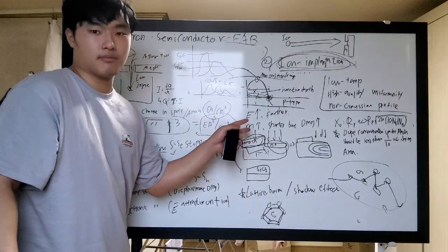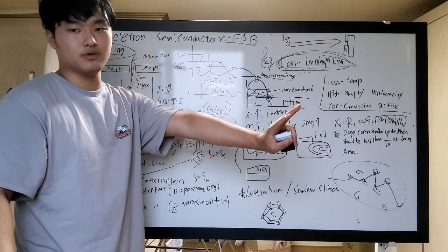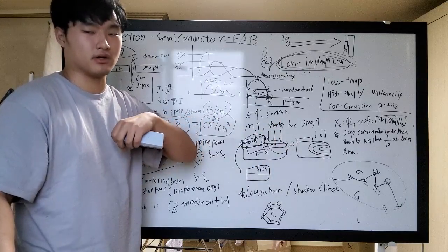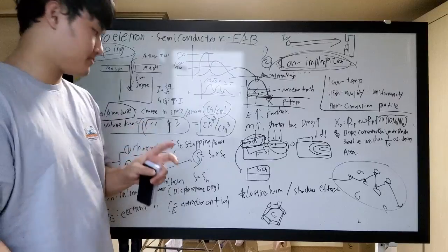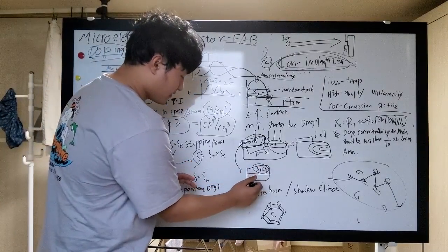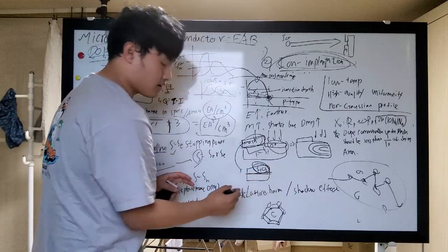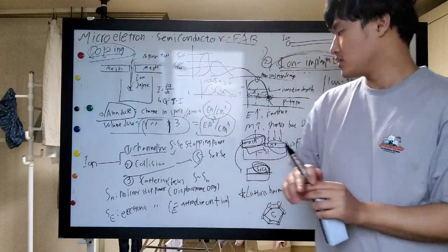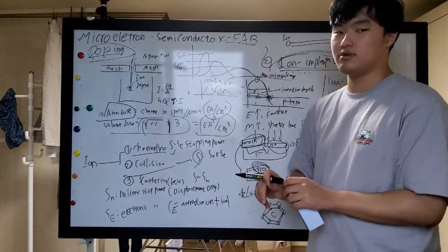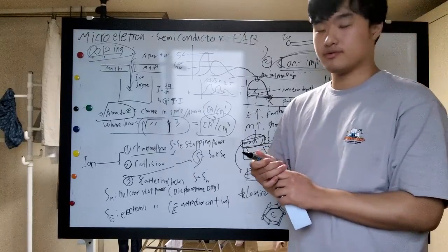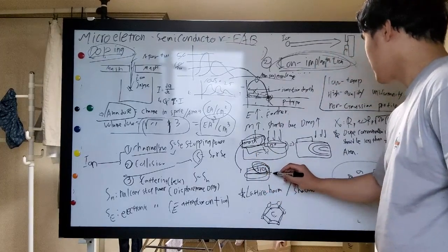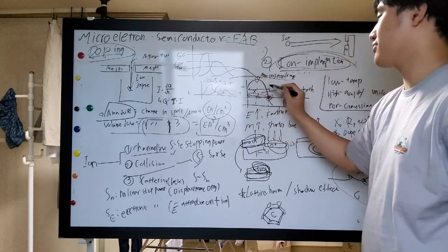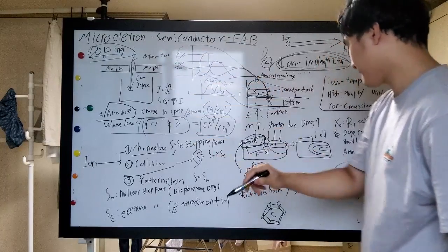So it means the mask will reflect the ions, or the mask will take the ions inside to be absorbed, so they do not reach the silicon underneath. For example, the dioxide that works as a mask will hold the ions inside, which means it has blocked them. Here, of course, the Gaussian distribution applies, like the graph I talked about previously.